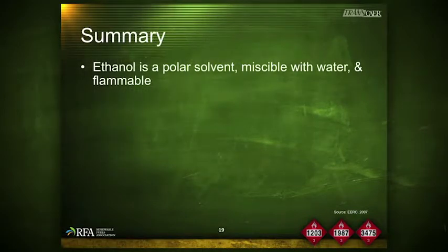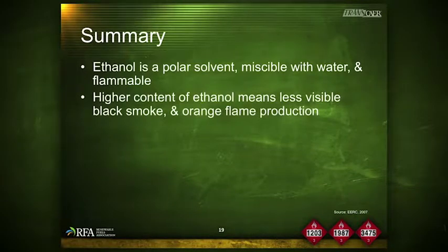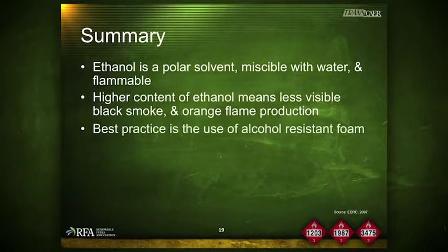In summary, ethanol is a polar solvent that is miscible with water and is flammable. Knowing ethanol will be the last fuel to burn and that it may burn with little visible smoke or flame is important in determining an approach to take in dealing with ethanol-involved incidents. The most effective route for keeping an ethanol fire under control is the use of alcohol-resistant foam, more commonly known as AR-AFFF. Because the AR foam is universally suitable for use on both ethanol and non-ethanol blended fuel fires, the best practice for responders is to keep an AR foam readily available for these incidents.